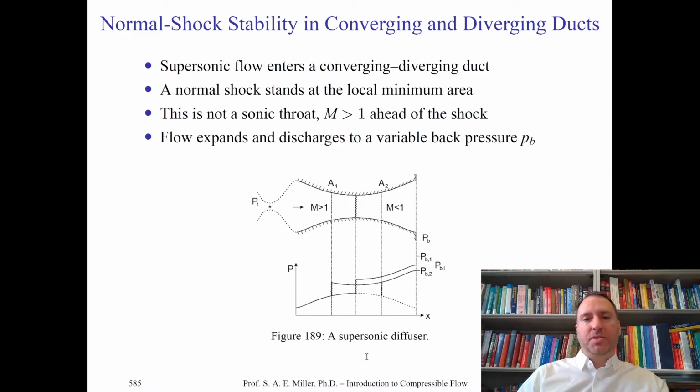Now we have supersonic flow through the diffuser. And to match the back pressure, we would need to have a shock wave form in this part of the flow. And so we started the tunnel and we pushed the shock wave from the first throat downstream. And by raising the nozzle pressure ratio, we push it downstream, just like we started the nozzle, and it ends up somewhere in the second throat. Here are 3 possible physical situations for this to occur.